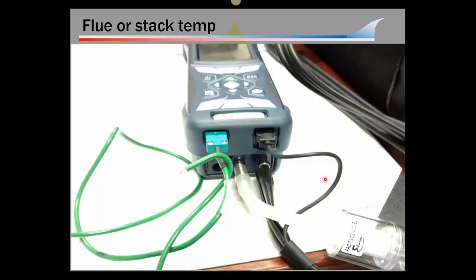And talking about that, here's another thing I found that a lot of guys were uncertain on. So this is my combustion analyzer. Over here is the temperature probe that goes out into the probe I stick in the flue. This gives me my flue temperature. Over here on every combustion analyzer is another, they call it a type K thermocouple, that I can put a temperature probe in. If this probe is not in this slot, then the machine just reads the temperature of the air around it. Okay? So if this machine is in my office and my office is 68 degrees and this is not plugged in, this machine is going to say, yeah, the air around me is 68 degrees.